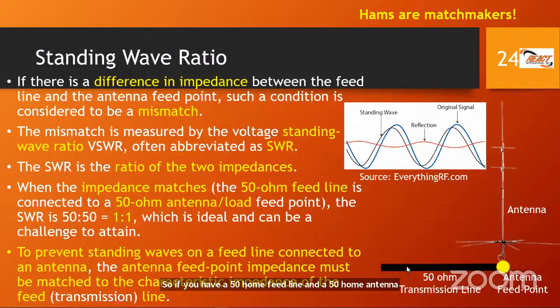And that is very important as amateur radio operators. Why? Because we are matchmakers, trying to match the transmission line characteristic impedance with the antenna feed point impedance.